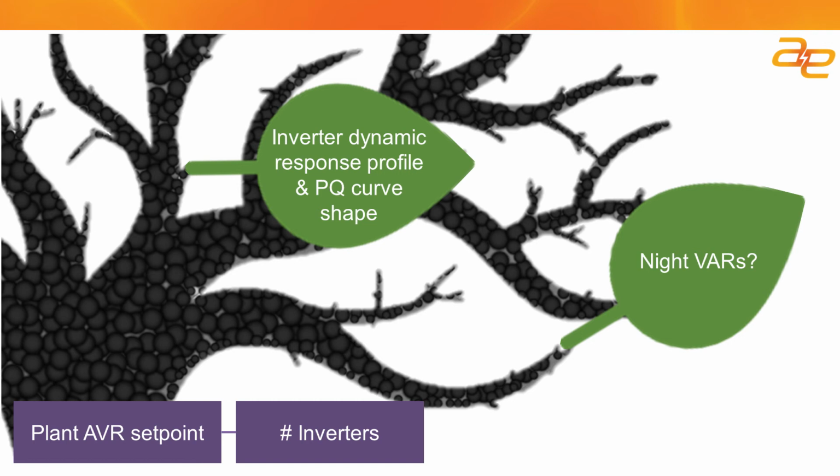So this is a capability that, again, lends itself well to ancillary services, and you may be able to participate in the spot market for ancillary services, or you may be able to get an agreement that ancillary services are required. But having the ability to make VARs at night or in very low light is something that didn't exist in solar power plants years ago, but it is certainly something that the control system needs to be able to control in order for you to participate in those markets. So definitely something that you should consider when designing your control system.